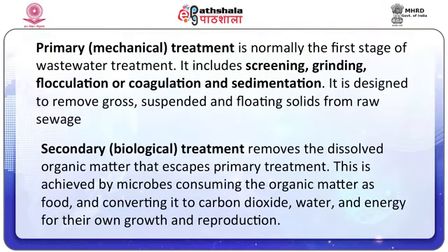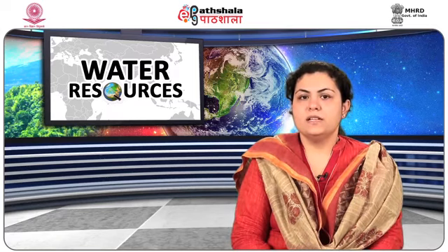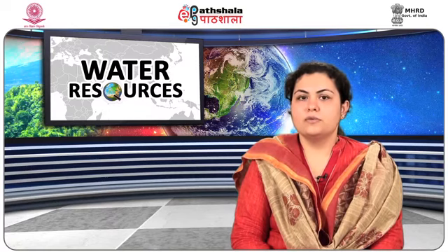Primary, which is the mechanical method of treatment, is normally the first stage of treatment of wastewater. It includes screening, grinding, flocculation or coagulation, and sedimentation. It is designed to remove gross, suspended and floating solids from raw sewage. In screening, big size suspended materials such as rags, wooden pieces, wires, etc. are removed.